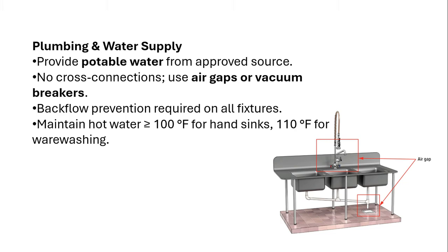A cross connection is, say you may have worked in a kitchen before, where they would literally hose the floors down to rinse off the floors to get everything to go down the drains. A hose is not a potable drinking supply, because once you make a hose wet on the inside, it will never ever be dry again. And what happens when you have things in dark spaces that are perpetually damp?